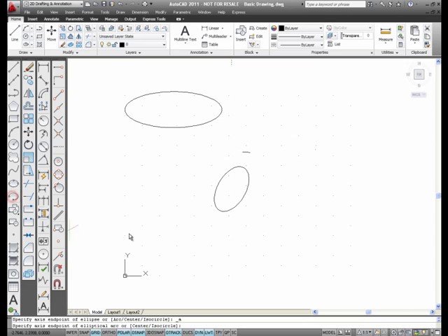Remember 3-point ellipse, you're going to pick. Notice, I'm still in isometric snap, but I can still draw these, approximate or the 3-point. I'm going to pick, let me pick on this side, and then there's my ellipse arc. This is the ellipse command.